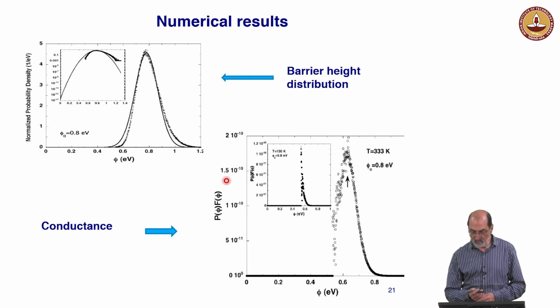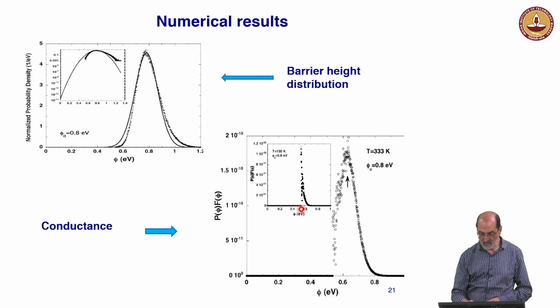And when you do that, you see that here it collapses. We don't have places where the barrier height is lower than, say, 0.55 eV, even though the average barrier could be 0.8. We don't have anything below that. So this is the distribution of the integrand. And if we go down in temperature, it's always the same. Below that we have nothing, and the distribution becomes narrower because the Fermi-Dirac function drops very fast, and at low temperature it goes faster.